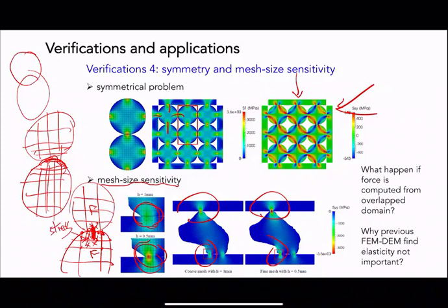Okay, because the finer the mesh, the closer you get to the singular point, and that is actually one of the problems. In the previous work on FEM-DEM, we never actually saw any major difference between the DEM and the FEM-DEM, simply because there is not enough mesh to capture the contact point in a very small area. In general, you may not have a point-wise contact, but a small area contact will also lead to a huge sensitivity to the mesh near the boundary.